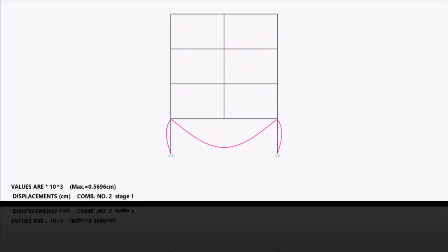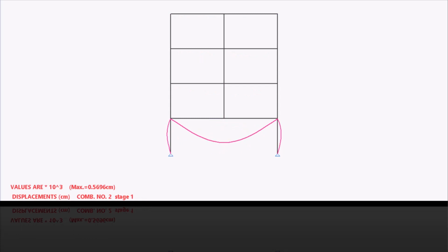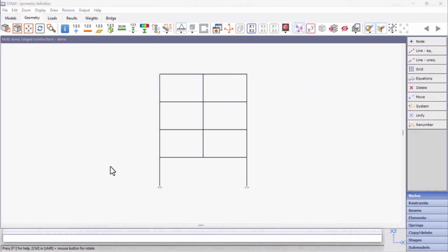When using the multi-story feature, the software automatically divides the model to construction stages and adjusts the calculations accordingly, ensuring that each construction stage modifies the structure's static scheme. The application of loads on the structure adjusts according to each construction stage, and the results of each stage are combined in the final solution. For example, for a multi-story reinforced concrete structure, where each floor is cast step by step, it would be correct to load the self-weight of the elements based on that construction stage.